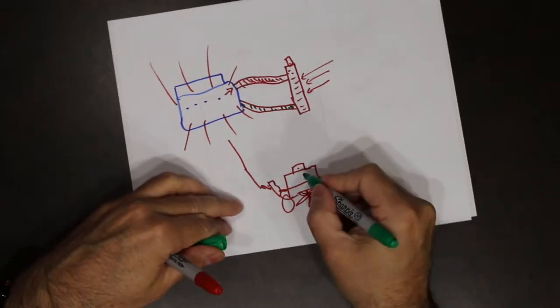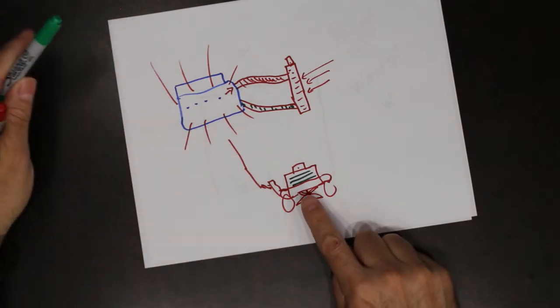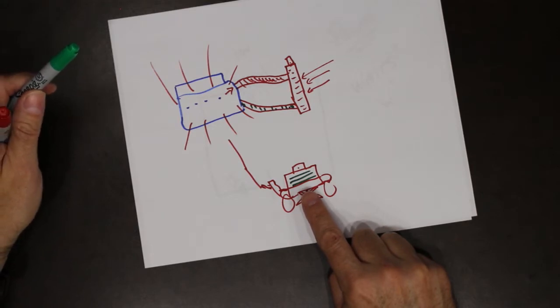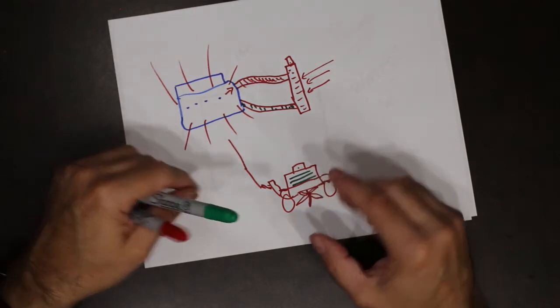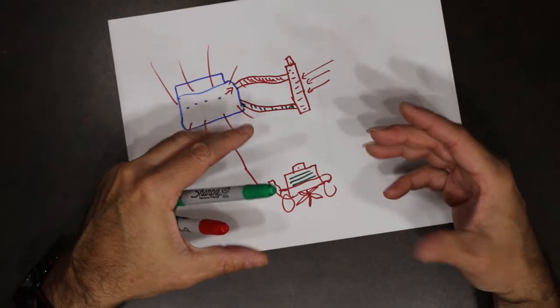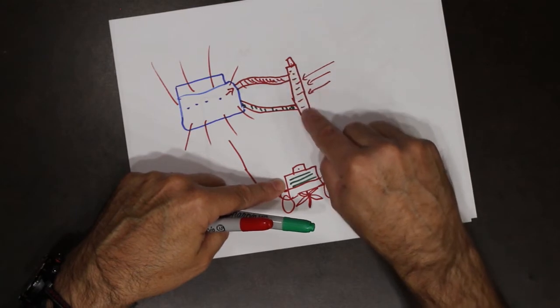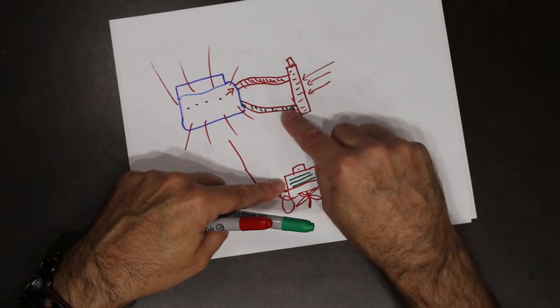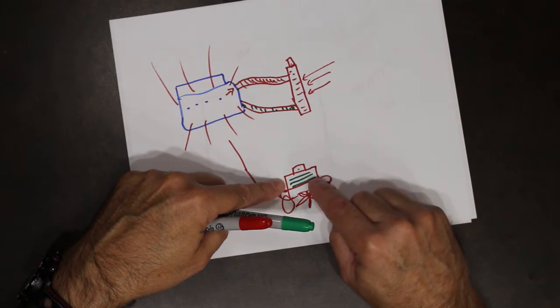But there are fins, what they call cooling fins, on the side of the engine. What that does, it increases the surface area so that the natural air can cool the engine. It's the same concept as the radiator. We have air flowing through the radiator to cool the liquid. Here we have air flowing past the engine to cool it.